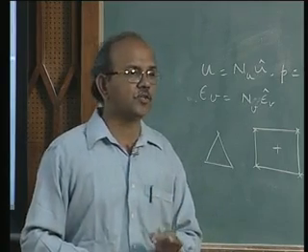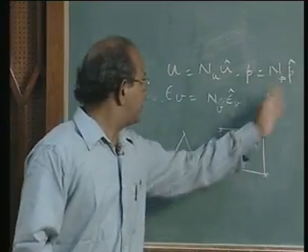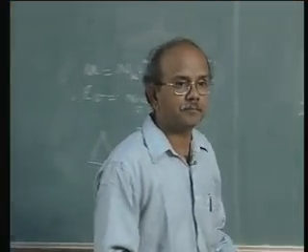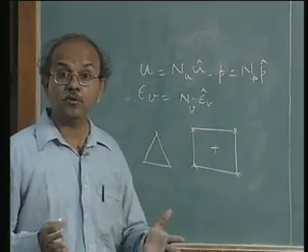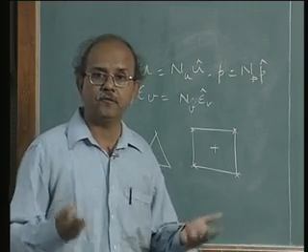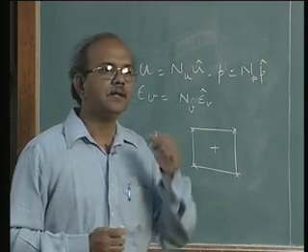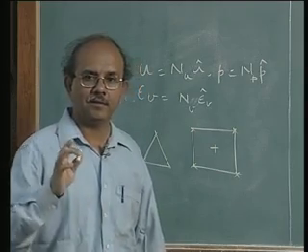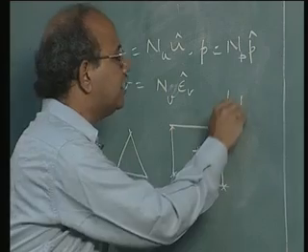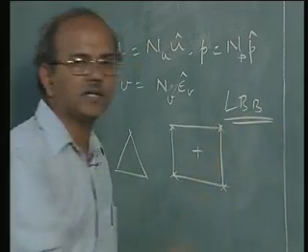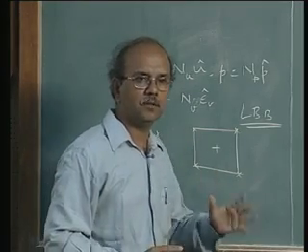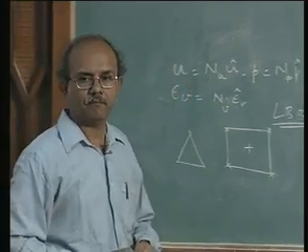We are talking about a situation where pressure as well as epsilon v are also to be interpolated. They can be different. Again, as I told you, this is due to certain conditions which I require, and we will call that later the LBB condition and so on. Let's not get into a lot more mathematics at this stage. Let us just look at the end result.